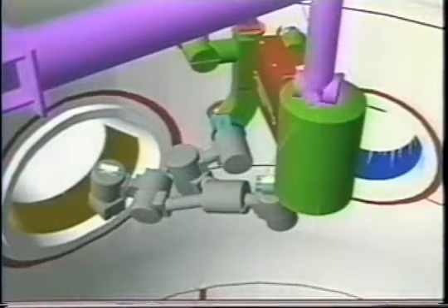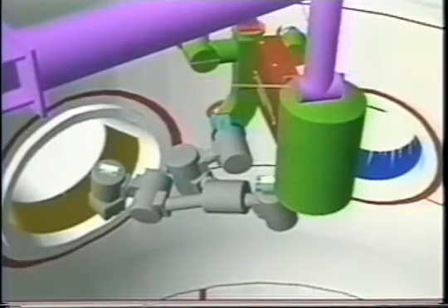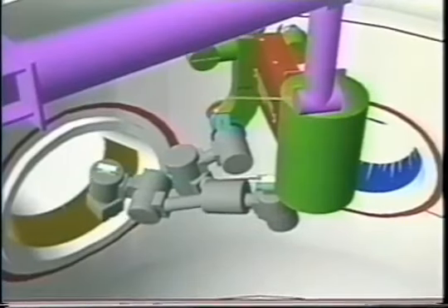The robot scan location must be known in vessel space. The vessel space positioning system aims a centrally mounted laser at the desired location. Ursula is then moved to place the photosensitive target close to the laser dot. The laser then searches a small area to locate the center of the photosensitive target. Tests have shown this system to be accurate within 1 centimeter.